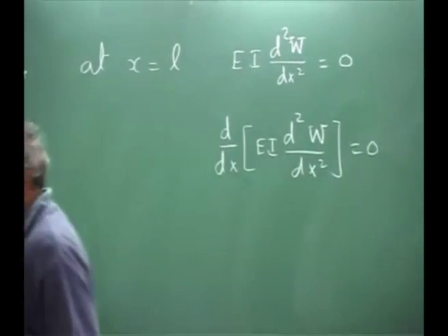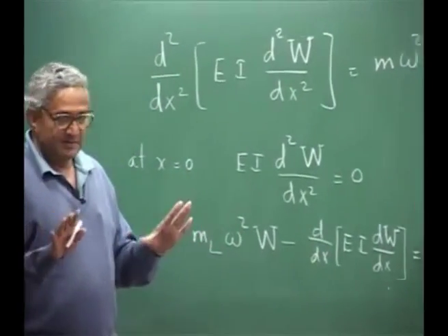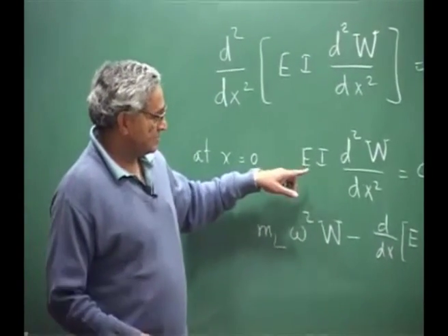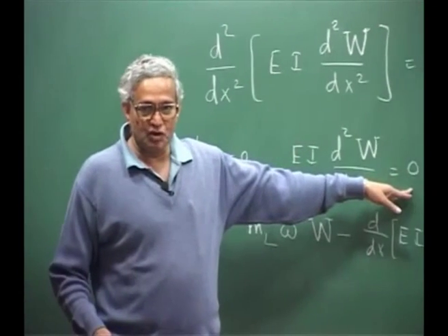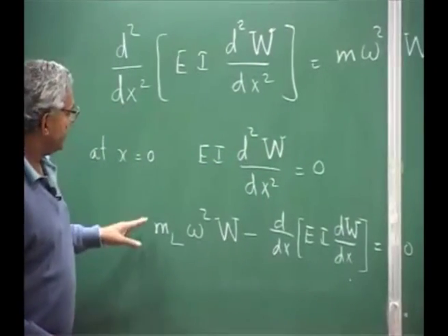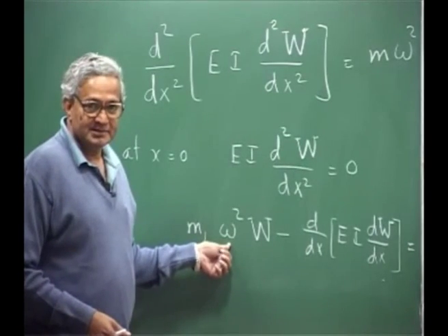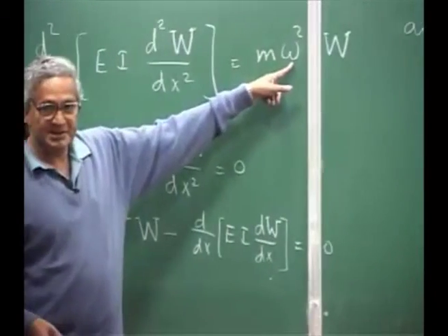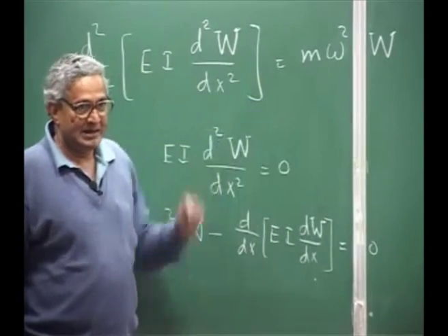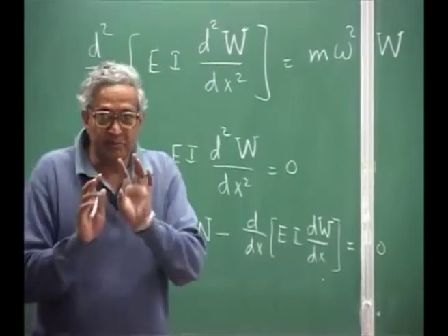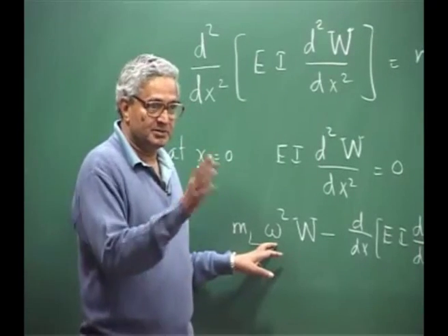But look at the form of the boundary conditions. In three boundary conditions, the right side is 0, the homogeneous case, whereas in one boundary condition there is an omega sitting in, which is again sitting in the field equation. That is why, depending on the problem, the omega can be in the boundary condition or it need not be in the boundary condition.